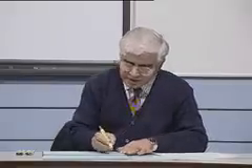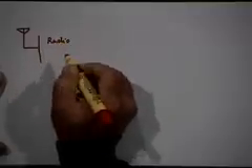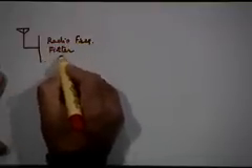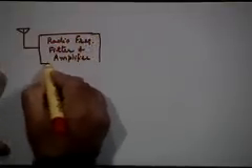So how do we select from this? I am giving the details now. Let me go through the process, and then if there are any questions after that, we will take care of that. So the superheterodyne receiver precisely does that. You have your signal coming in from your antenna. The first stage has to be the radio frequency stage, which carries out the initial filtering. So this is the radio frequency filter and maybe some amplification. Remember that filtering has to be done for two reasons: one, to reject other signals, and the other to remove noise, out of band noise, right? Noise which does not lie in the message bandwidth. The noise that lies in the message bandwidth, you can't do really very much about it. It has to come along with the signal.